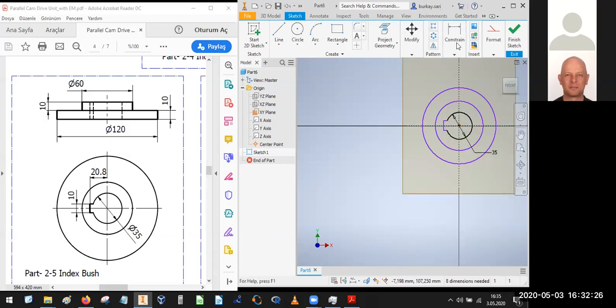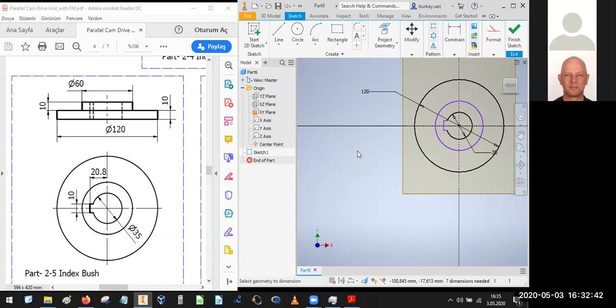For this purpose, it is better for you to just define the biggest dimension which you have seen. Here I am going to just make the alignment, and the biggest circle here probably have the 120 millimeter, which I have just get this from the other view. Also, we have another one which is 60 the diameter.